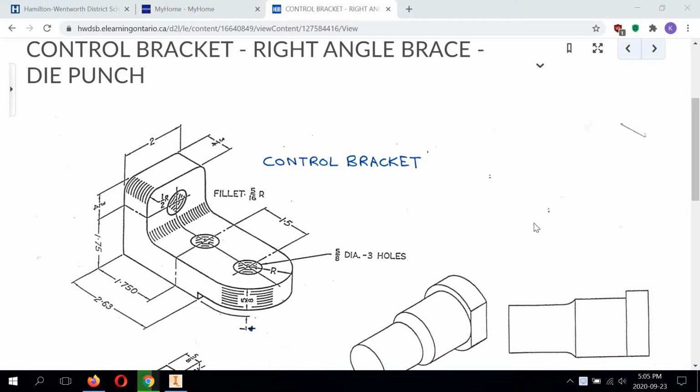So taking a look at this, it's a mixture of fractions and decimals, which is no big deal. That's not going to cause a problem for us using Inventor. But one or two things that students have difficulty with in this part model creation is the radius of the front, because all it does is point an arrow from the origin of this hole to the front arc, and it says R, and students become very thrown off by this. They say, I don't know what that radius is supposed to be.